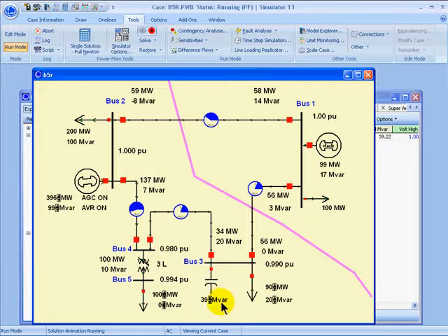And if I change this to where I'm actually producing megavars at my load, I'll eventually get to a point where my switched shunt has to turn into an inductor, and the symbol changes on the one-line diagram. The following slides contain some more detail about the example that we just went through.